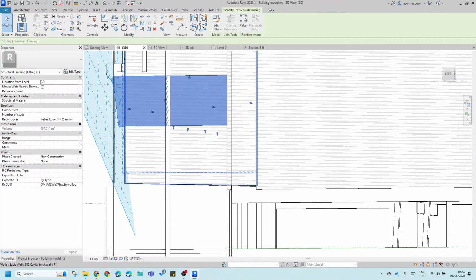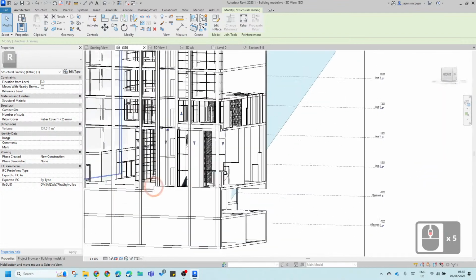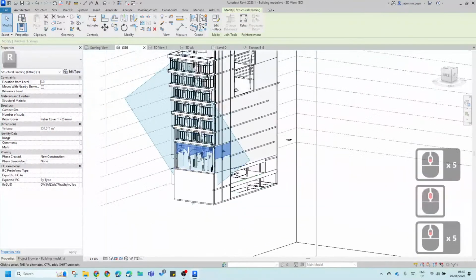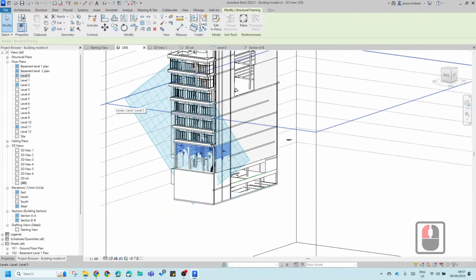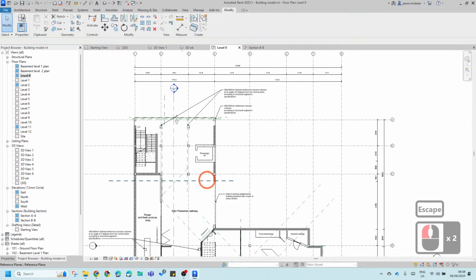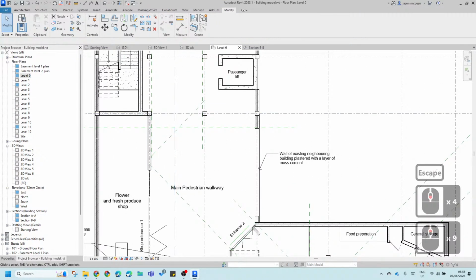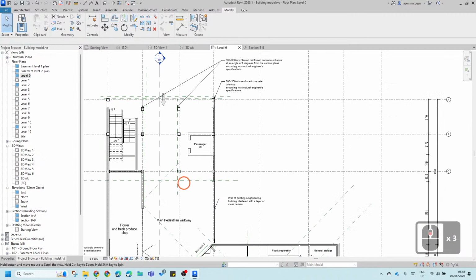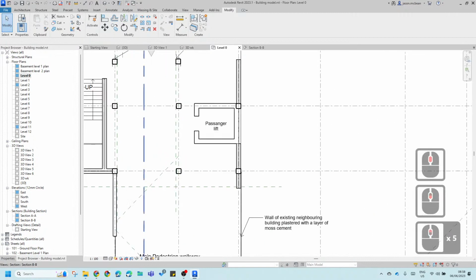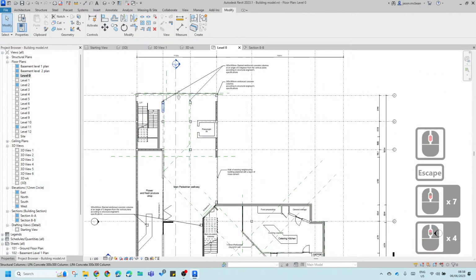Basically at the back where it folds back at the 45-degree angle, do I just pull it through and then build a cut void? Yeah, you can pull a void in plan and then cut it away. Let me show you that. So let's go to basement level. So you want to pull a void over here where it cuts it at an angle when you come in. Yeah. So let's just go back to that.